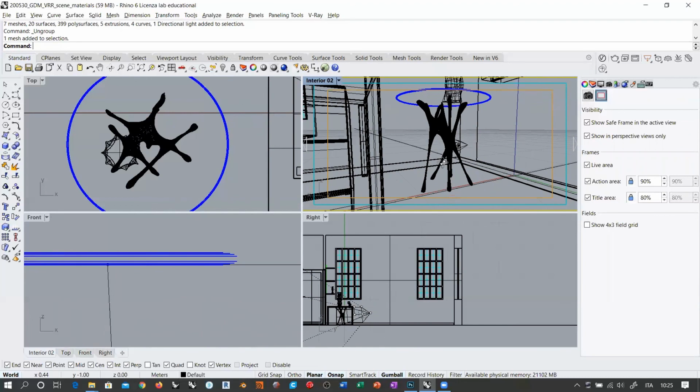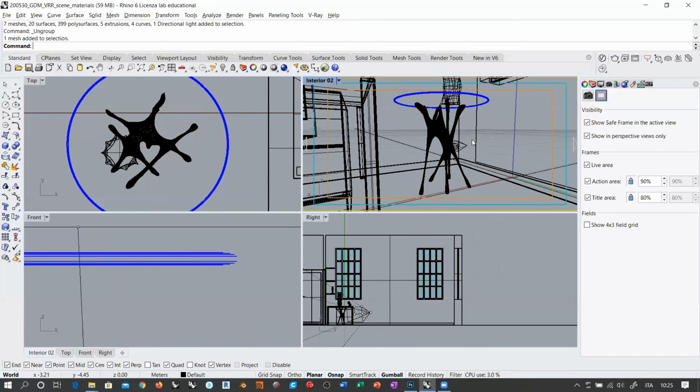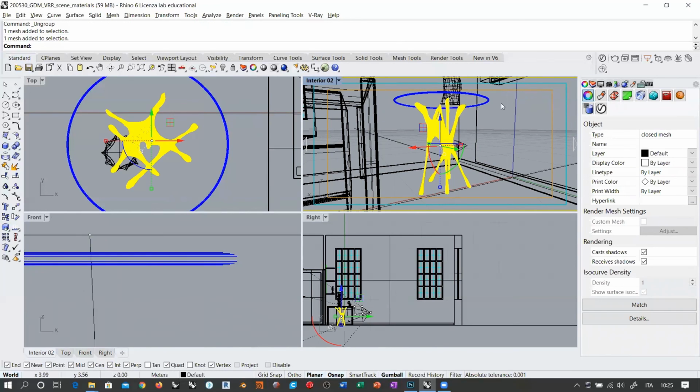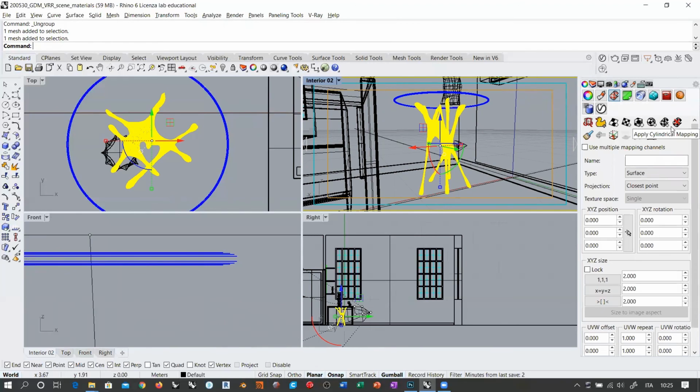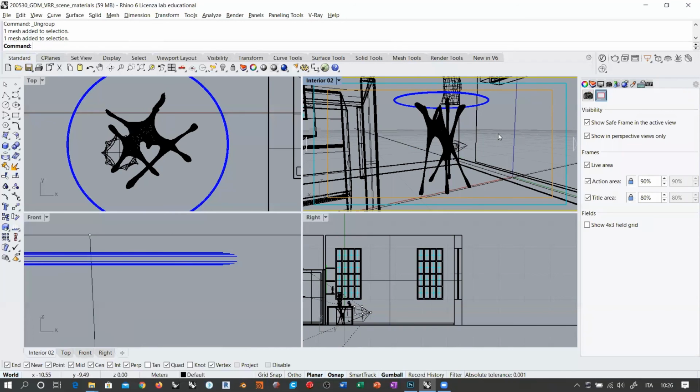Not here in Rhino. In Rhino, right now with V-Ray, you have two options. Of course, as we did already, is applying some primitive texture mapping that takes into account the different orientation of this object in space. And the more likely we are going to work with spherical mapping as we did. But there is another option which is available since the latest versions of V-Ray.